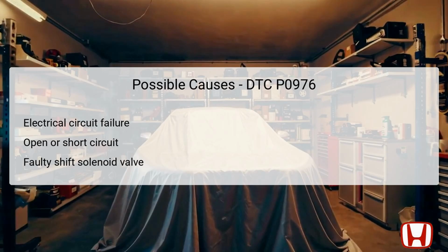Regular inspections of the wiring harness and connectors are crucial, as even minor corrosion or frayed wires can trigger this DTC, indicating the importance of good electrical integrity within the system.